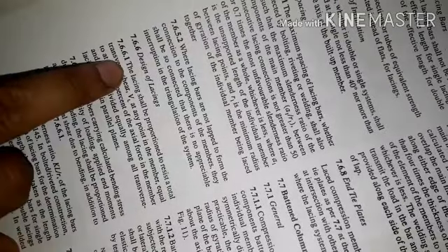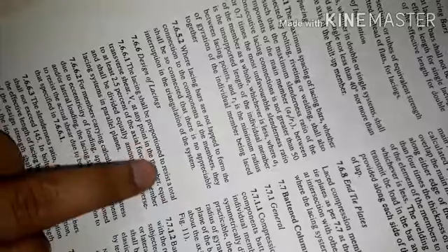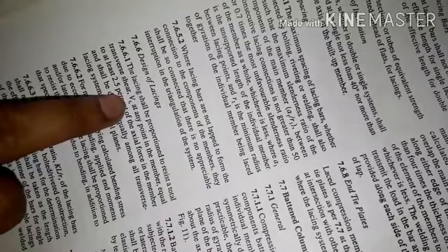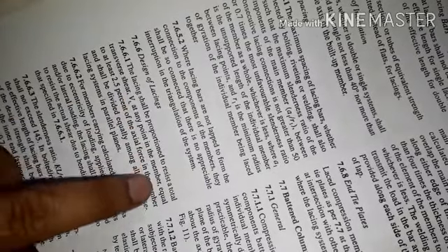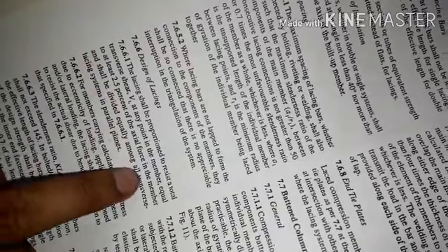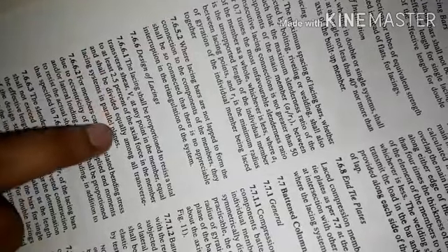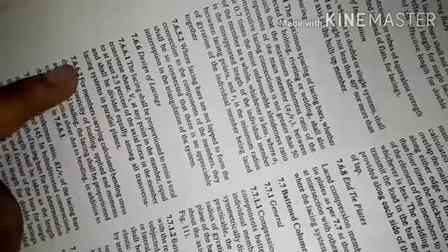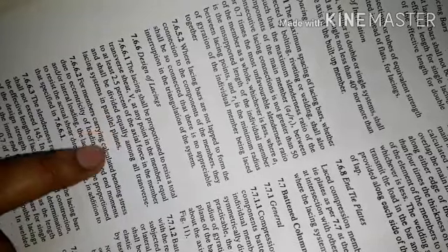Here the lacing shall be proportioned to resist total transverse shear Vt at any point in the member equal to at least 2.5% of axial force in the member and shall be divided equally among all the transverse lacing systems in the parallel planes.